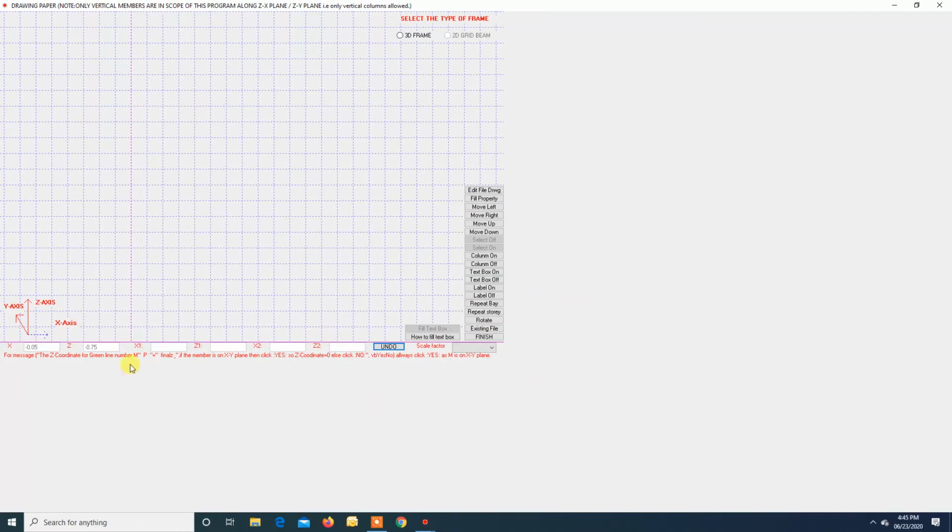So this is a page. Okay, so this point is 0 0. Sorry, first of all we have to select the scale, because if you don't select the scale, then the computer will take it by default and then you will not be able to change it. So before you start drawing anything, first select the scale. Say 1 unit is equal to 1 meter. This is 1 unit. We are taking this as 1 meter, right? So let us select this. Okay, so this is the starting point, right? And that is 0 0 over here.